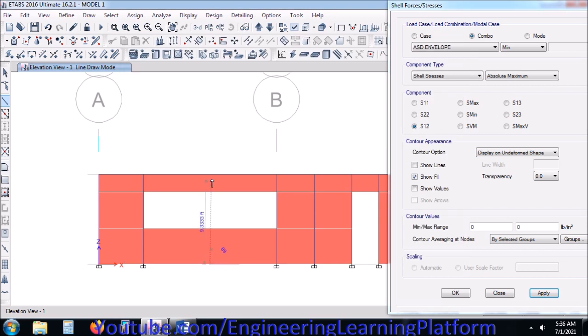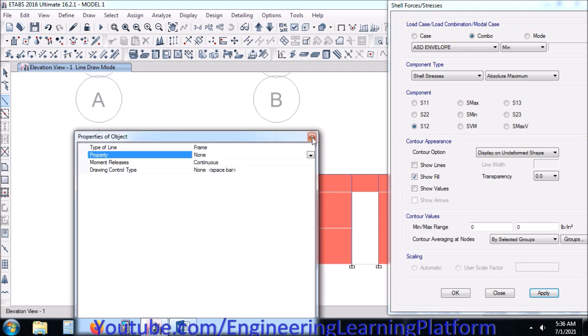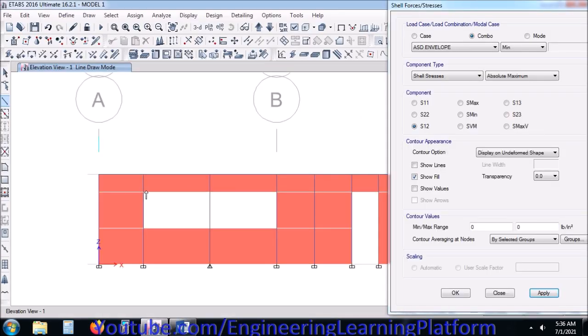So I am adding a reinforced concrete edge here in order to reduce the shear stresses, and it's a big span for a masonry only. So I have added a reinforced concrete edge here, and similarly adding the lintel beam here, which I ignored in the previous modeling techniques. Let's match these frame elements and combine the column again.